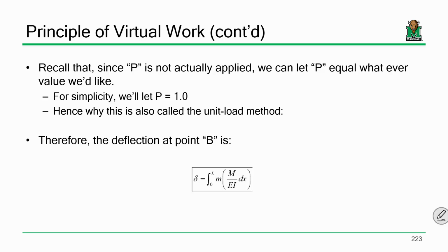Point three, we eliminate this 1/2 term by employing a principle of virtual work as opposed to a principle of real work. By doing that, not only do we eliminate this 1/2, but it allows us to not compute the deflections just where the loads are applied, but we can get the deflections anywhere. Everybody okay with that? Okay.